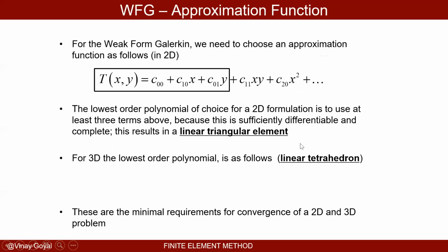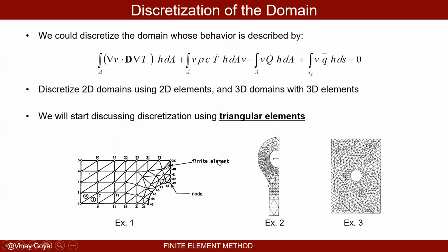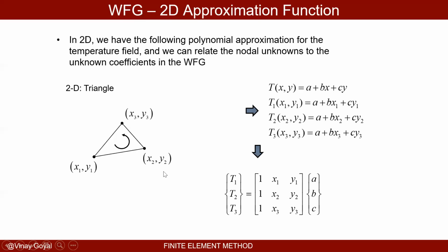Because when you look at this problem, you do know the nodal coordinates of that triangular element. So just to make sure you understand, we know X1, Y1, X2, Y2, and X3 and Y3. We know them. And I don't know the temperatures, but we can presume we know them at the nodal locations, and try to figure out what A, B, and C are in terms of T1, T2, and T3. Because with that information, I can try to figure out what my shape functions look like.